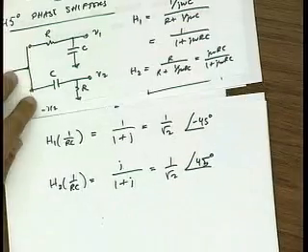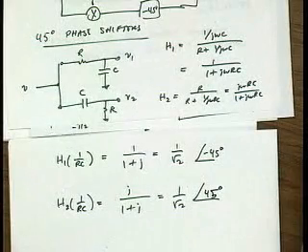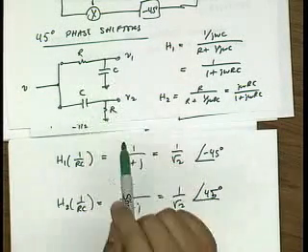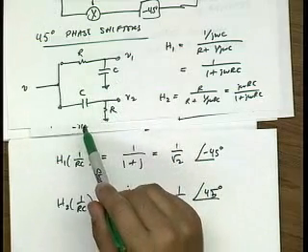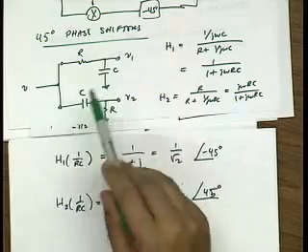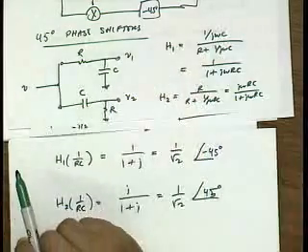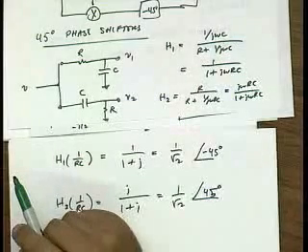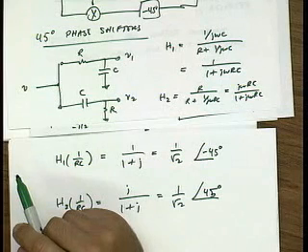Okay? Question, Kevin? Yeah, so typically are R and C going to be tunable? You have a good point. As we've drawn it, this only works for a single frequency, so it would only actually work for narrowband signal. If you want to make a broadband version of this, it's basically a polyphase filter. You can do a multi-section version of this, and you get more broadband capability. I guess my question is, if we're not going to tune it, why not just have a longer piece of trace for one of the signals?